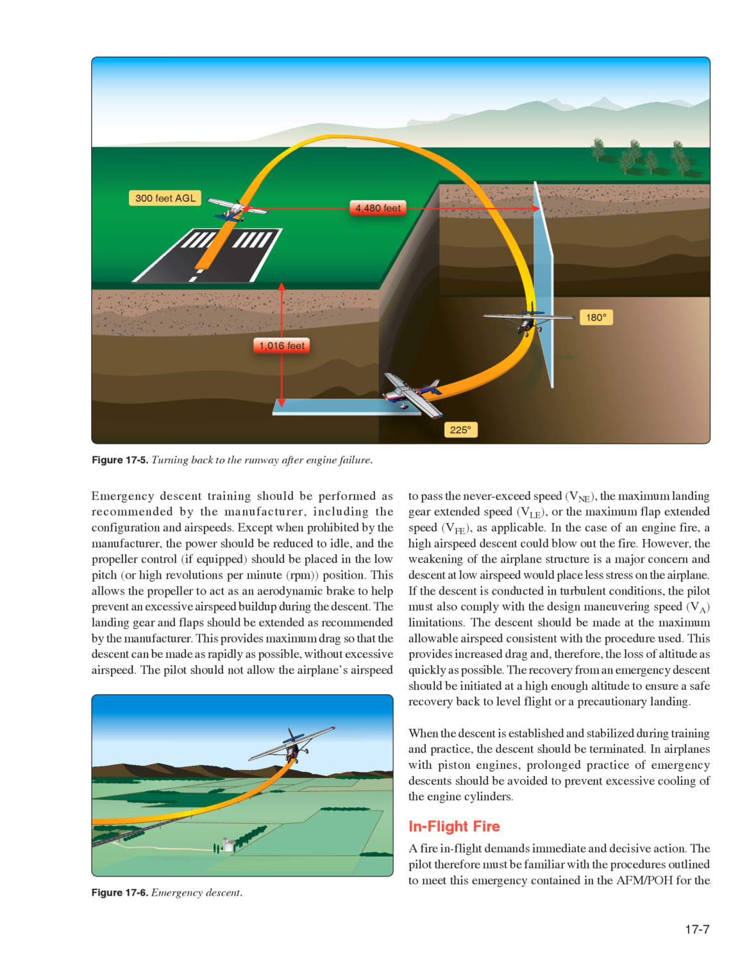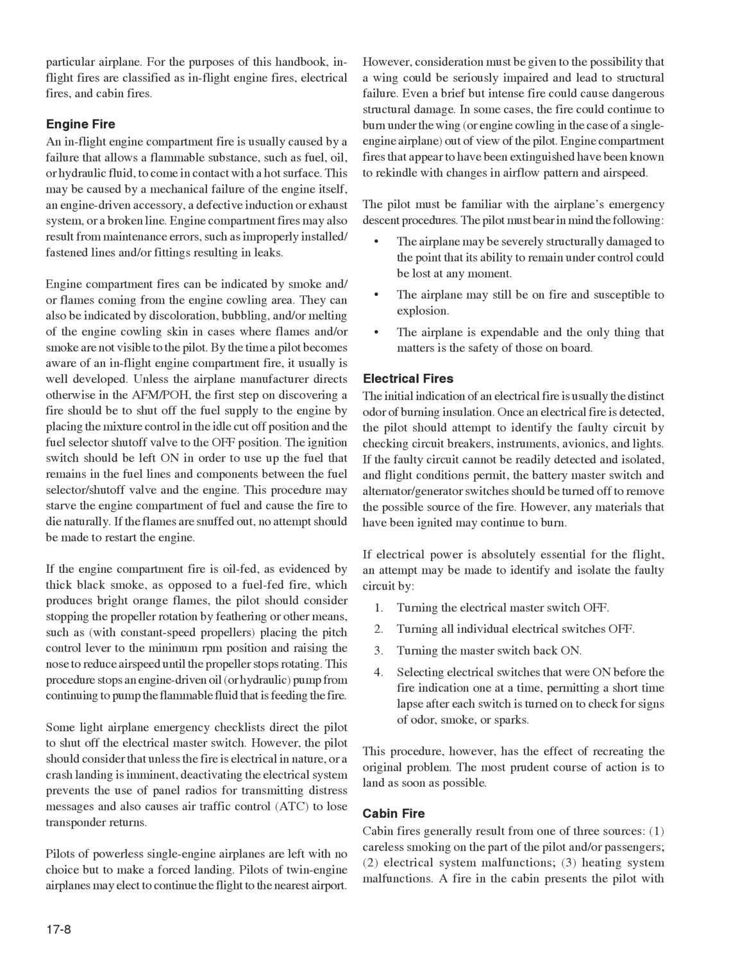In-flight fire: a fire in flight demands immediate and decisive action. The pilot therefore must be familiar with the procedures outlined to meet this emergency contained in the AFM/POH for the particular airplane. For the purposes of this handbook, in-flight fires are classified as in-flight engine fires, electrical fires, and cabin fires.